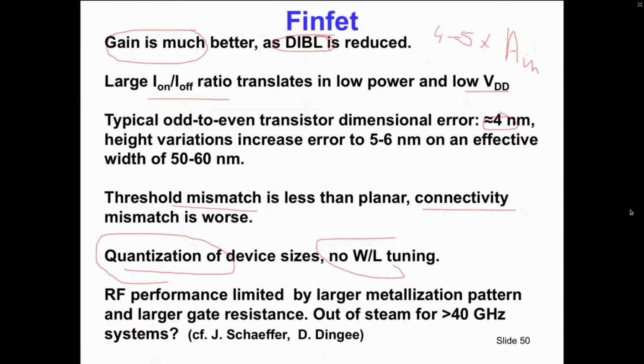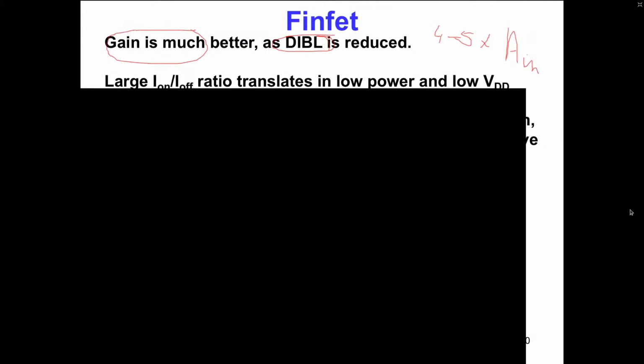The metallization patterns and the gate resistances are at this moment a bit of a headache, because some people claim that 40 gigahertz is roughly the max that you can do with FinFET. Whether that claim is standing over the years is not yet clear, but that is the opinion at this moment.